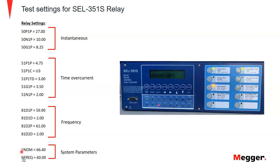And then I need to give some parameters of what the system is going to be like. So our nominal voltage here is set for 66.4, and then our frequency here, since we're in the States, is going to be 60 hertz. Okay.